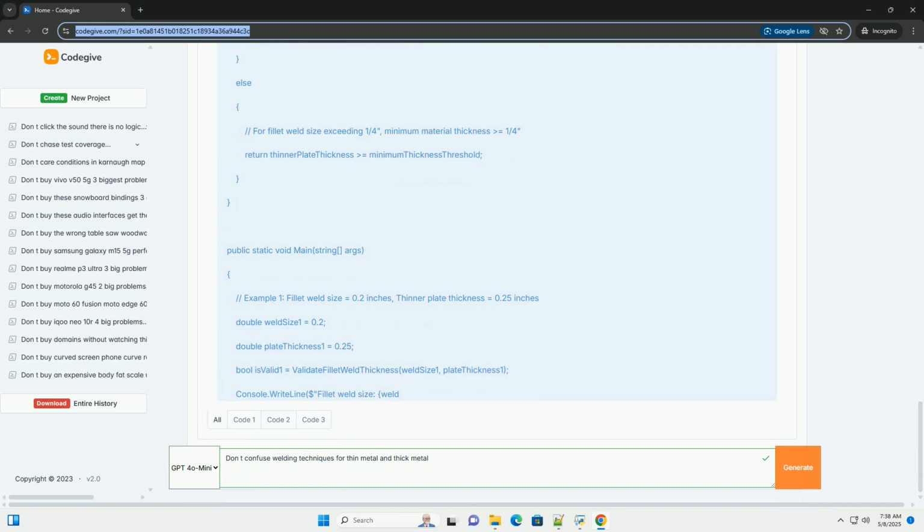Lack of fusion, thick metal: increase amperage, slow down travel speed, improve edge preparation, or use a weaving technique. Porosity: clean the metal thoroughly, ensure proper gas shielding, and use a low hydrogen electrode, SMAW. Undercut: reduce amperage, improve electrode angle, or use a weaving technique. Cracking, thick metal: preheating, proper joint design, and using a compatible filler metal can prevent cracking.